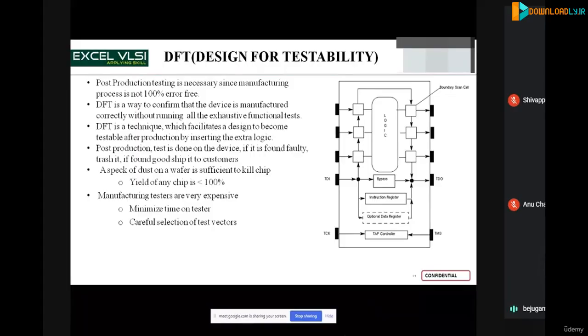It is done because once the circuit is completely implemented, we can't find the fault in a simple gate, as picking a gate and checking it is impossible. So if we do this in the earlier stages, our chip can be fabricated without any faults.